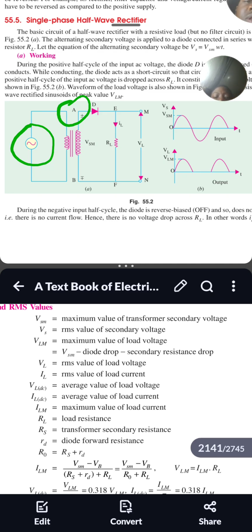Okay, so you are going to convert it to what? Now this VRMS, using that 10:1, you convert it to VRMS for the secondary. It's ready for primary. Let's say you have 230, because mostly it's always 230. Let's say you have 230 for the primary as the VRMS. It's always the VRMS that's here. Now, divided by, let's say you have 5:1, divided by what? N2 over N1, which is simply 1 over 5. Okay, sorry, multiply by 1 over 5, which is the same thing as divided by 5.